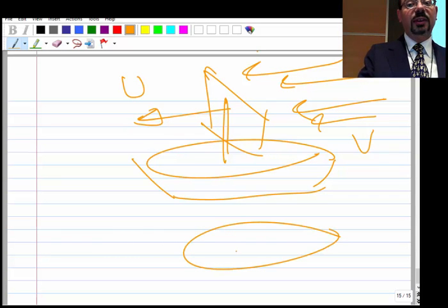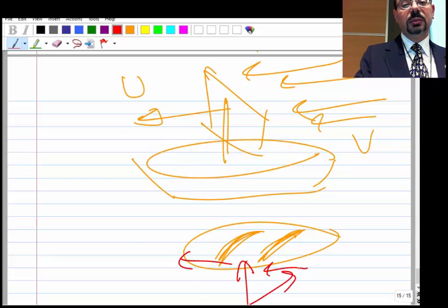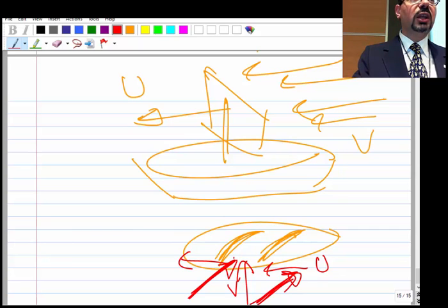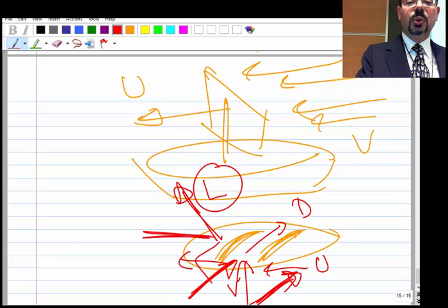Right, so their sail would be based on a lift force, right? So you would be like here, but because it's moving this way, this would be the W. This is U-boat, this is the V of the wind, and this is W. So this W over here would come like this, and it will generate lift, which direction? Normal to the wind, and drag in the direction of the wind. So it is this lift force, the horizontal component of it, that will propel the boat faster.